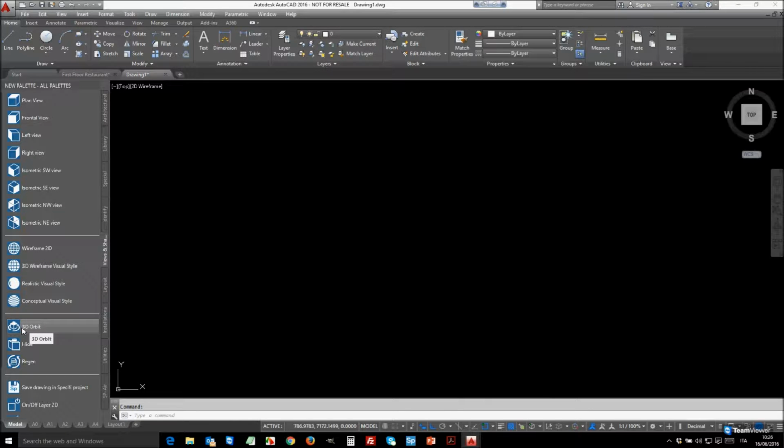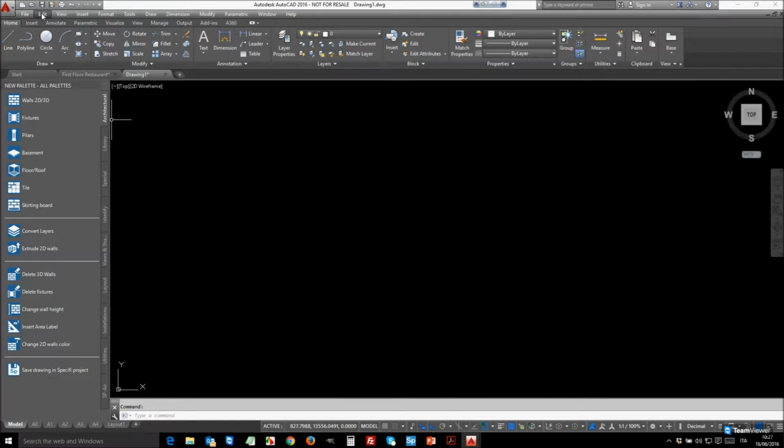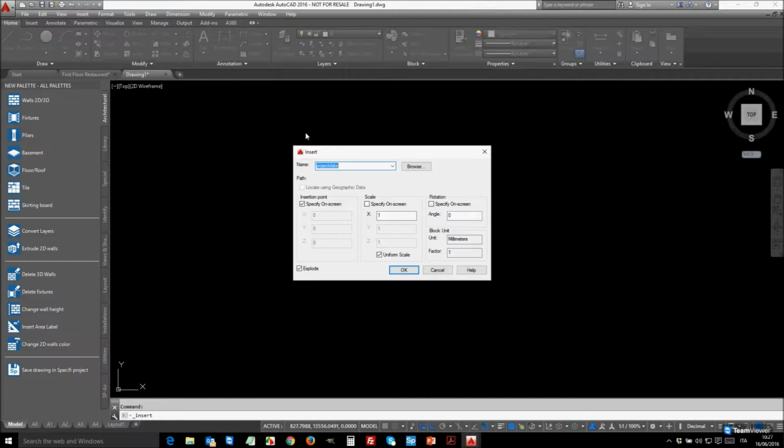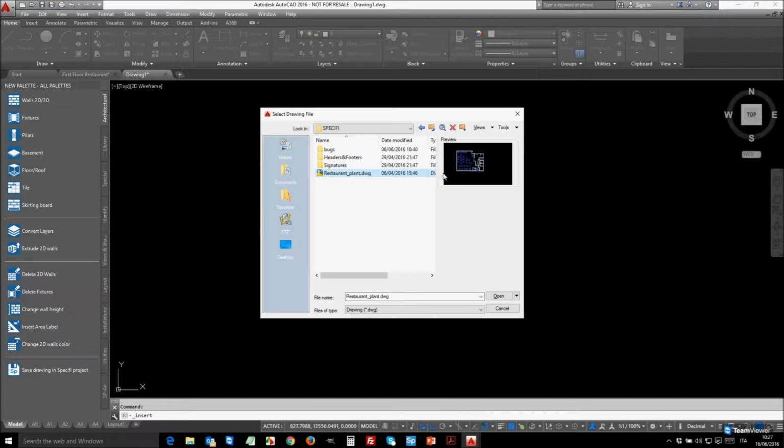Okay, and Identify. So the next step is to identify the area and to assign the position number to each equipment. And then View and Shade: we can change the point of view from plan view to isometric viewport, or apply shadow, or use the 3D AutoCAD standard commands to rotate our environment. Then we prepare the layout, moving into paper space to create the layout and print our drawing. And then we can manage the installation point or MAP drawings.